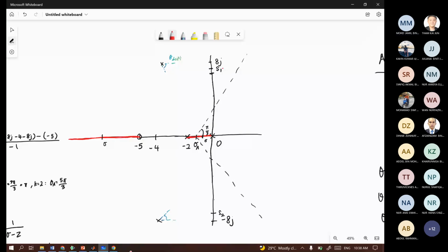S1 and S2 are the j omega axis crossing. If you want the root locus to cross this crossing, you must make sure that it will cross this but not cross the asymptote.